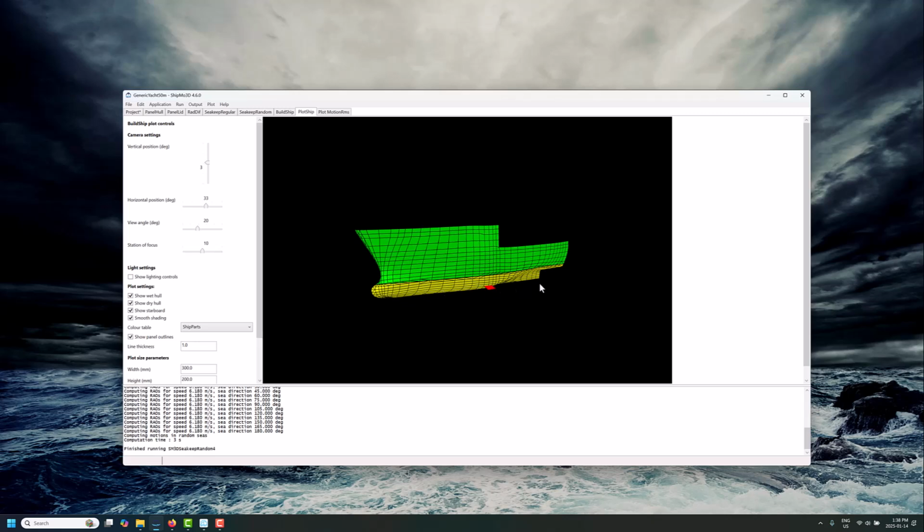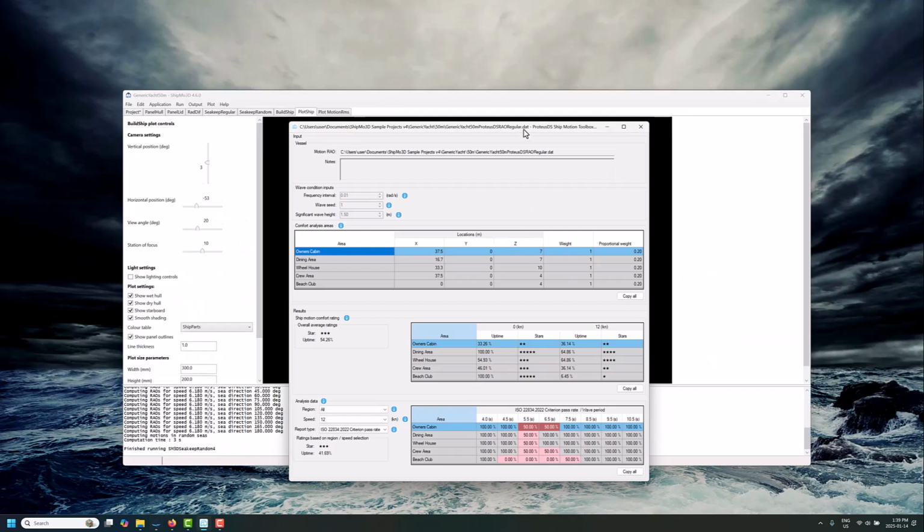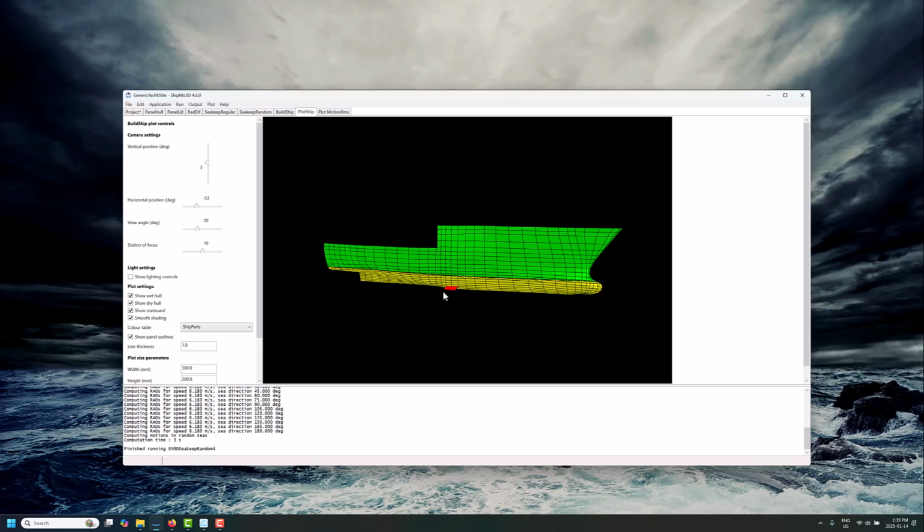This creates a hydrodynamic force that's going to apply forces to the ship and affect the ship motion in the seakeeping and also the time domain seakeeping maneuvering analysis in the ShipMo3D toolset. It's also going to affect the motion RAO calculations, which then get used in other calculations like in the Ship Motion toolbox and so on. We'll talk more about what all those implications are. But one thing I want to highlight first is some of the limitations.